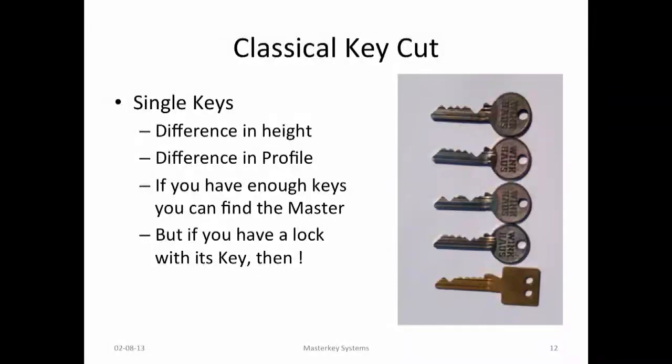So you see some keys from the system here. Also nice, this is an easy entry key for the system. These key blanks are also available, but this key blank is milled completely out. So even if we have a restricted keyway that's not available anymore, with an easy entry system I can make this key in 10 minutes. So even key blanks from systems that are not available can be made.